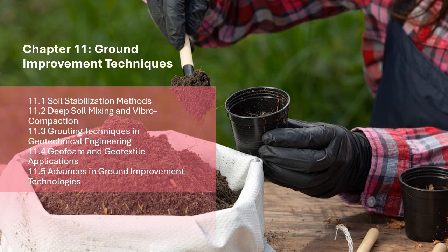1.3.1.4 Chemical grouting. Chemical grouting involves the injection of chemical solutions that react with the soil or groundwater to form a solid mass or reduce permeability. The chemical grout may harden or bond the soil particles together, increasing the strength and reducing the potential for settlement. Materials used: sodium silicate, polyurethane, acrylics.